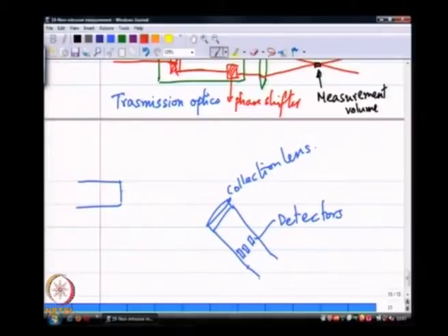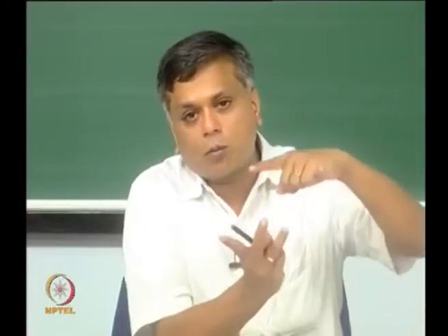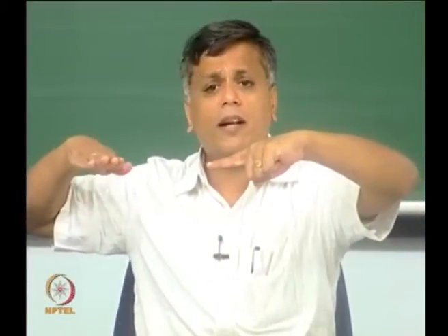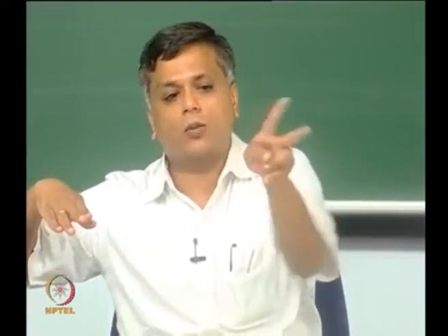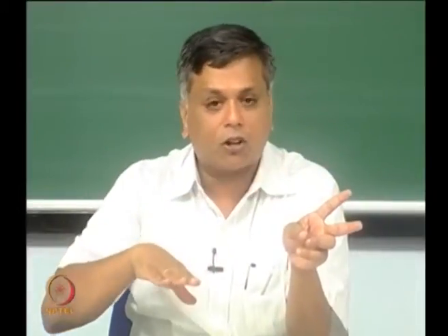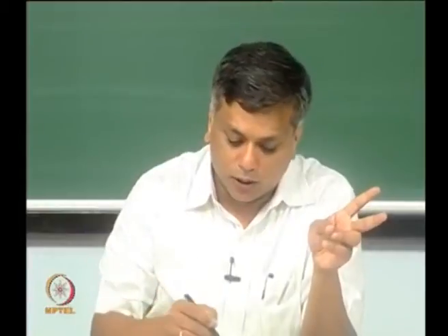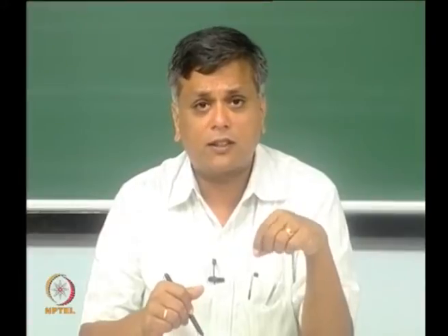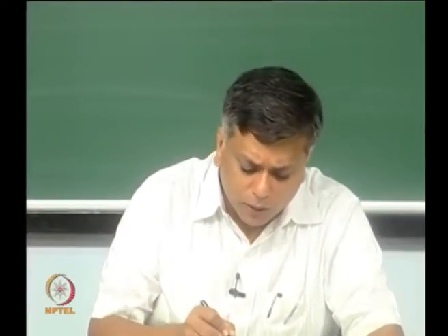Now, I am only going to draw one laser beam here, but you would have to imagine that the plane of the beam is perpendicular to the plane of this sheet of paper. So, I do have 2 beams that are intersecting in this way, and the receiver is placed where my right hand is. In the plane looking from the top where I can draw the receiver, the receiver is, as you can see, slightly off angle, and in that plane the 2 beams of light are coming in and intersecting at this measurement point here.